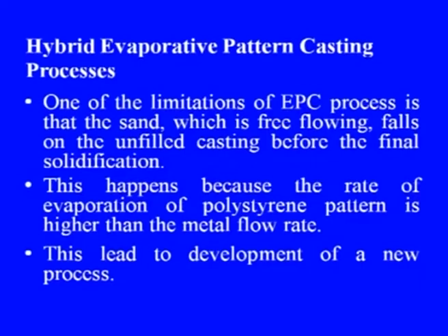We have already seen while discussing the evaporative pattern casting processes that in evaporative pattern casting process, sand which is free flowing falls on the unfilled casting before the final solidification. This happens because the rate of evaporation of polystyrene pattern is higher than the metal flow rate. This led to development of a new process.